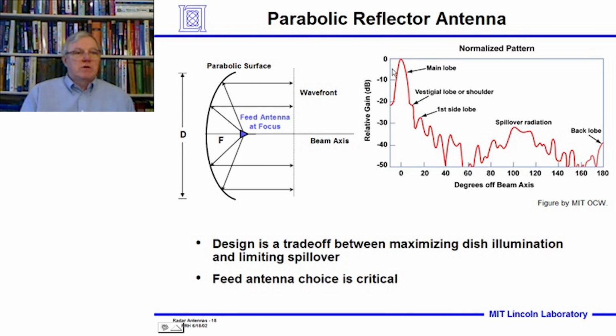What I'm going to focus on here is the issue of the trade-offs that go on, and how you design where you put the antenna. Well, you have to put the antenna pretty much at the focus. You have a little bit of leeway one way or the other, but then there's how you design this feed. Because if we make the feed too big, some of the energy will spill over, and we won't efficiently have the energy reflect off the parabola and go out.